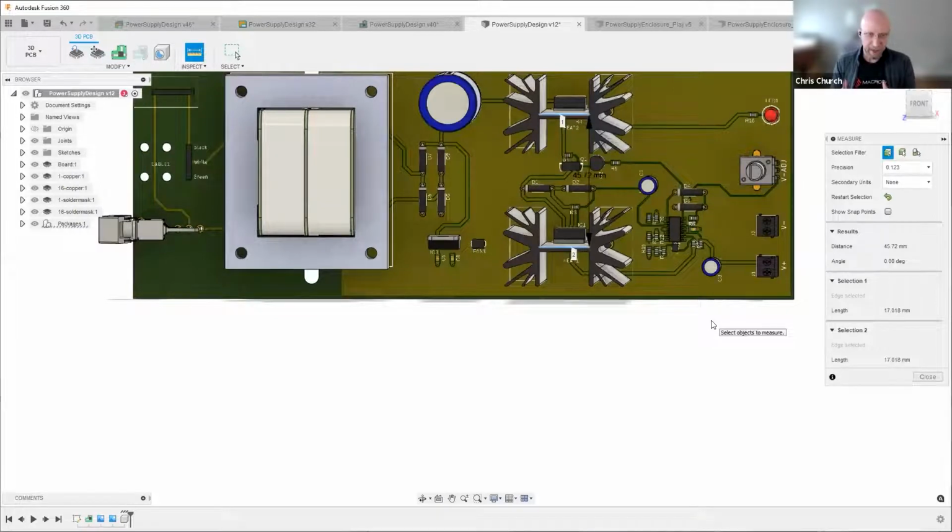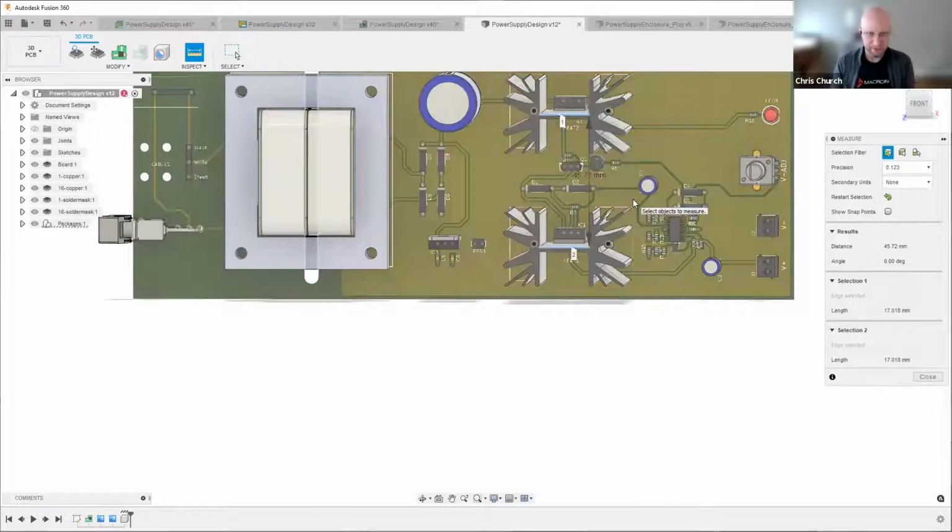And if we think about how, as a physical process, we'd have to assemble those, where we're going to be ending up is we're going to have to get a screwdriver in for that bottom one, right? Because it's going to go through that TO220 into that threaded hole. By measuring this, we can see that I can't actually fit a screwdriver between those two things. So I'm going to be bumping against that other TO220 or screwing in at an angle. It's going to be very challenging.